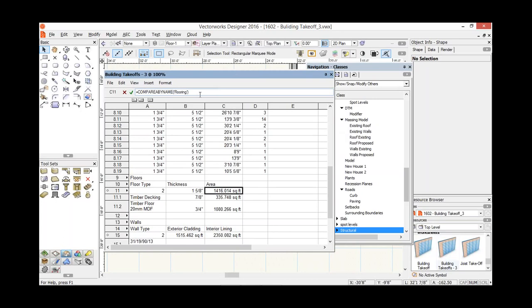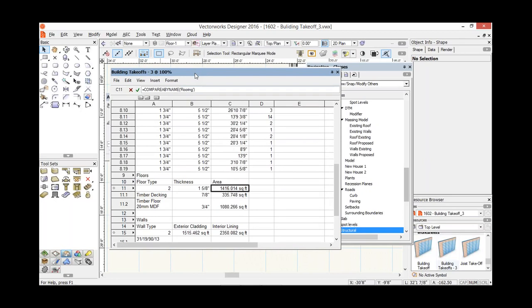But to come back to what I said, if you've created one single slab and it's the entire building, that's what's going to be reported. So if you want to create a slab with a component just for the tiles, you'll have to create a small area of slab that is just the tiles. You might find it easier to use your floor finishes plan with polygons and look for the area of the polygon.